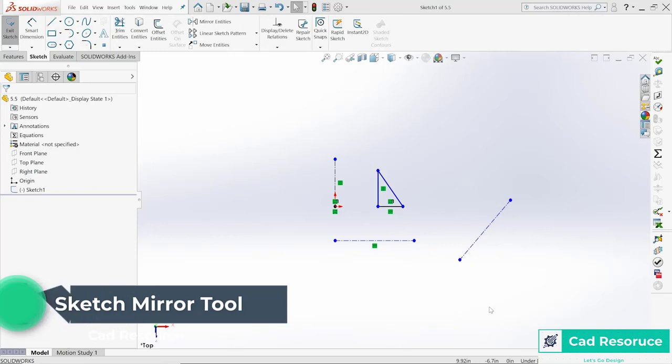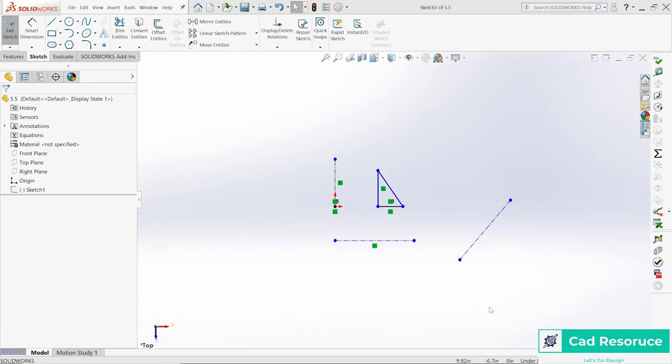If you're trying to create an extruded body, for instance, I could mirror over this triangle here and extrude it out, and then I'd have two individual bodies, but I could also do that as a solid. So, I generally recommend trying to keep your sketches very simple and then doing any of those mirror commands actually as mirror features when you actually have a solid, but you can do it either way. So, right now, let's focus on mirroring it inside of a sketch.